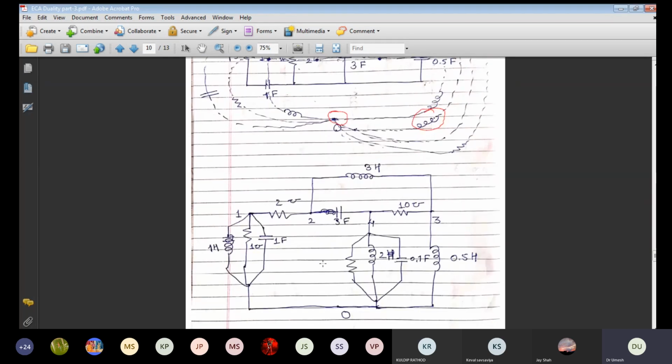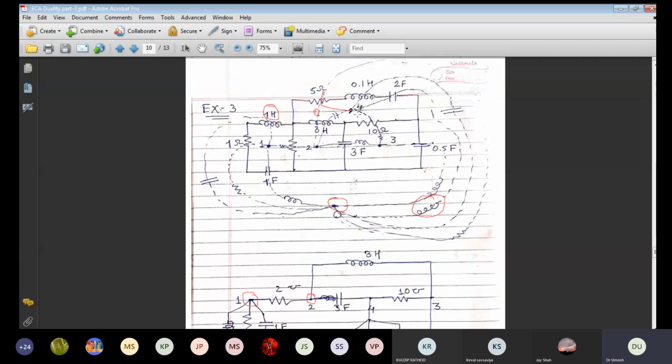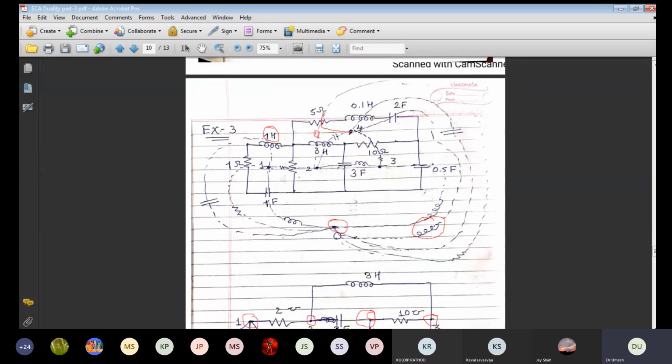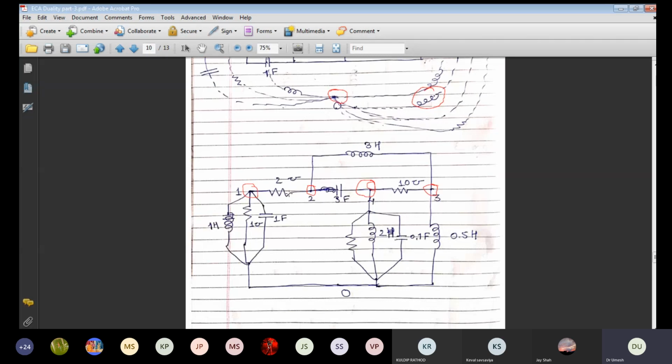So we can say that here node 1, node 2, and the 4 is coming in between, so we have kept it in the middle, 4 and this is third, right. Now how many go from 1? 1, 2 and 3 parameters. So look, how many go from 1 to ground, datum: 3 parameters, 1 is inductor, 1 is resistance, 1 is capacitor, right. We have replaced 1 ohm with 1 mho. We have replaced 1 Henry with 1 F, and we have replaced 1 farad with 1 Henry.